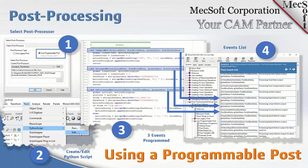If you go to the Tools tab in Rhino, just select the Python script, load your script, and you can edit it directly from inside of Rhino. It's basically a Python script editor, but you can have your own script editor. It doesn't necessarily have to be tied to Rhino. There's a lot of third-party editors out there that are pretty good as well.